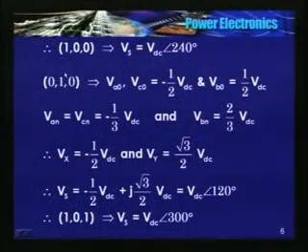Okay. So we will find out for one more case, and I can use the complementary of this vector, and I can get the position of the space vector. So the last one being 0, 1, 0. Only the upper device of B phase is on, A phase is off, and C phase is also off.